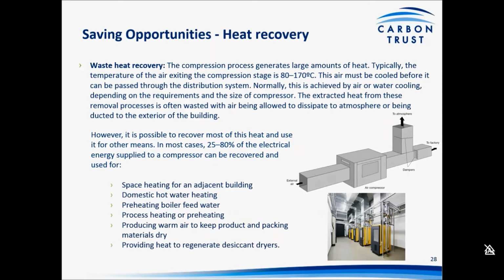But to talk a little about the opportunity for waste heat recovery. Depending on the compressors and the pressure you're generating to, the air exiting can be upwards of 80 degrees, and for the higher pressure machines up to 170.